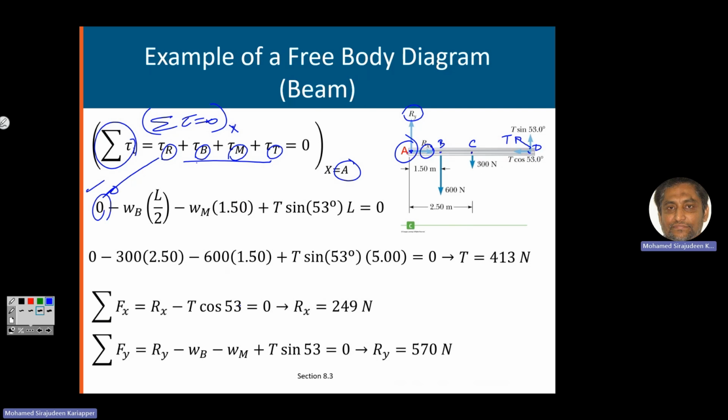Torque from the weight of the beam is here, right? So r will be, if I choose green, the distance from the pivot point to where the force is applied, and it is equal to 2.5 meters. But anyway, at this point I will just write L/2. If the length is L for the beam, it is given as 5 meters. So 5 divided by 2 is 2.5, but let me just put it like that. Multiply by the weight of the beam.